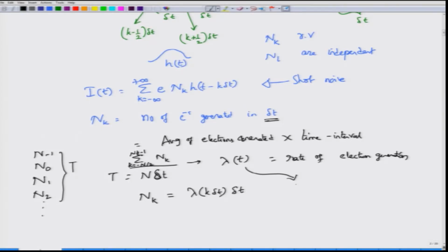Well, we said that electrons are going to be generated depending on how many photons are converted into charge carriers, and that depends on the quantum efficiency eta. So, eta times the number of photons, which would be given by P over h nu. Please note that nu is equal to Fc in our case. However, I am going to use nu because h nu gives me the energy, which is something that I am used to. So, this would be the rate of electrons that are generated.